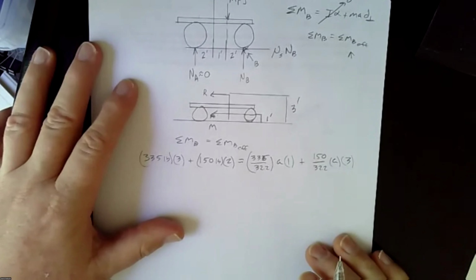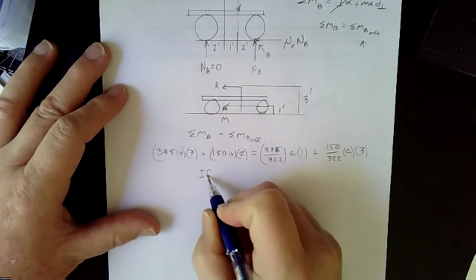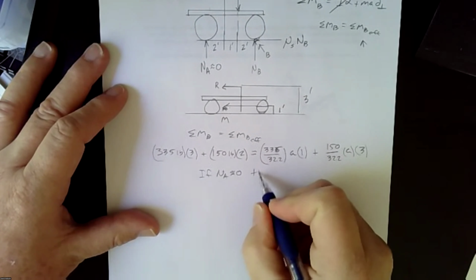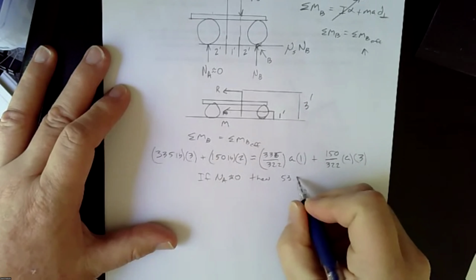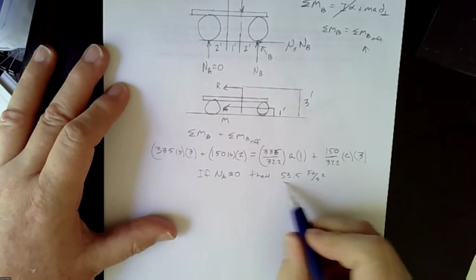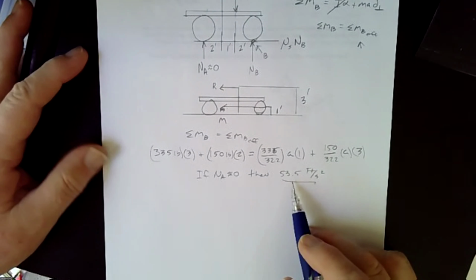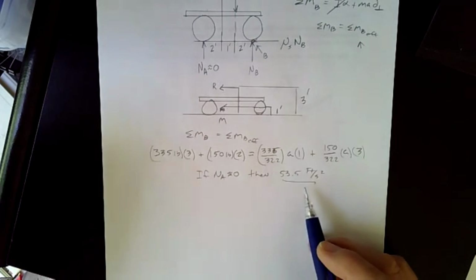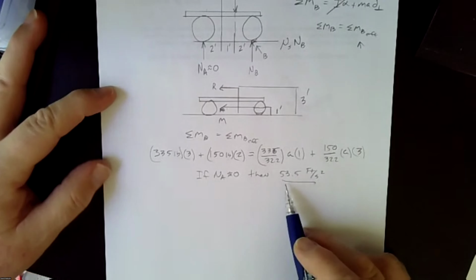Okay. So we're saying if NA is 0, then our acceleration turns out to be about 53.5 feet per second squared. So now think about that practically. 32.2 is a G. So this is like a 1/3 of a G. And if you've ever ridden an ATV or motorcycle, you don't accelerate that fast. That's more like a roller coaster or maybe a drag car if you're into that.